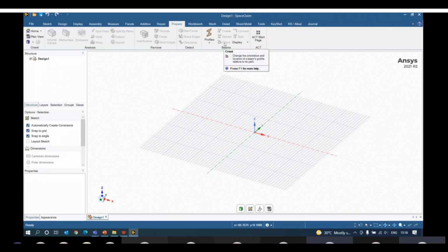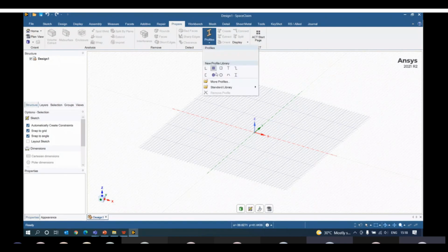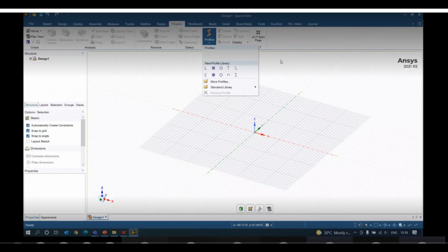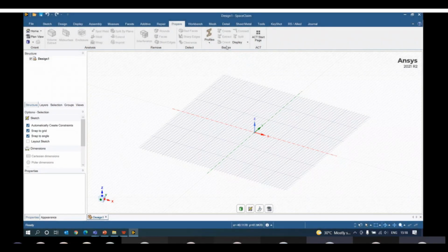And let's say someone is working on some problem related to beams. There are certain standard libraries existing, out of which you can take those cross sections directly and use them, or you can also extract them from the existing 3D models. And you need not worry about connecting those beam models, because you directly have a beam connectivity which will help you in terms of continuity and the load transfer, what we talk about in terms of beams. So that also you can do very easily.